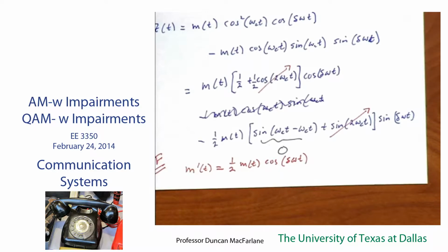That's really distorted, right? That's 1 part in 10 to the 5th. And it brings you right into baseband. And so that gives you the tolerance. That's a very, very severe impairment if I'm allowing these two local oscillators to run without talking to each other at all.